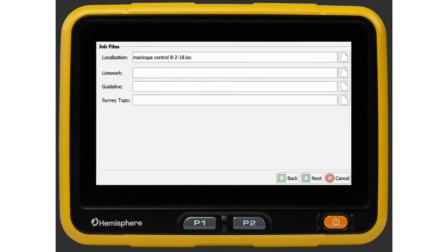Sometimes you will find the northing, easting, and elevation of the control on the plans, or you'll have to request them from the project owner or general. When you get the control information, you'll have to shoot each control point using a rover. All this does is equate a specific lat, long, and height to a known northing, easting, and elevation. Once complete, you save it to a thumb drive and bring it into Grade Metrics.